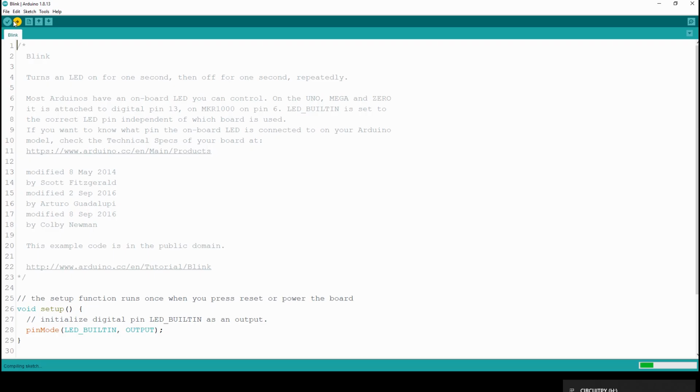If you change your mind and you want to use the board with the Arduino IDE again, all you have to do is to upload a sketch to it using the Arduino IDE. The Arduino bootloader will be uploaded automatically to it.